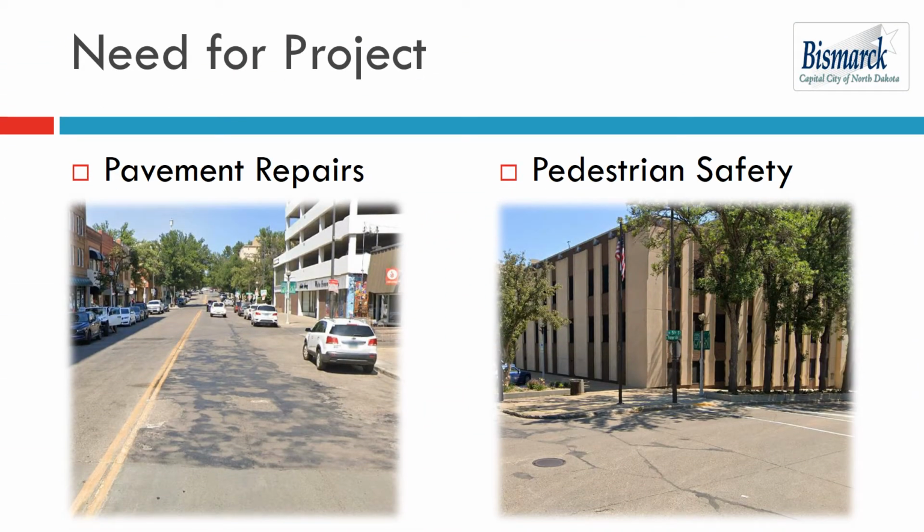The primary purpose of this project is concrete pavement repair. Concrete repair and general maintenance has been performed, but there has not been a dedicated street rehabilitation project on any of these concrete streets. The pavement within this project has deteriorated beyond a level that annual maintenance or other lower cost rehabilitation strategies would be effective.